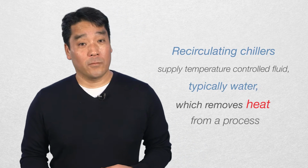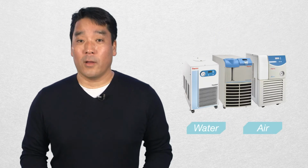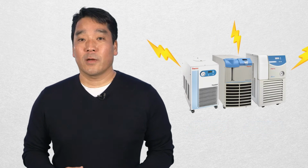Today we're going to talk about how to determine the amount of heat a recirculating chiller adds to the room. Recirculating chillers supply temperature-controlled fluid, typically water, which removes heat from a process. This heat is then transferred by the chiller to water or air. Electrical energy used by the chiller is also converted to heat, and for air-cooled chillers is added to the room.